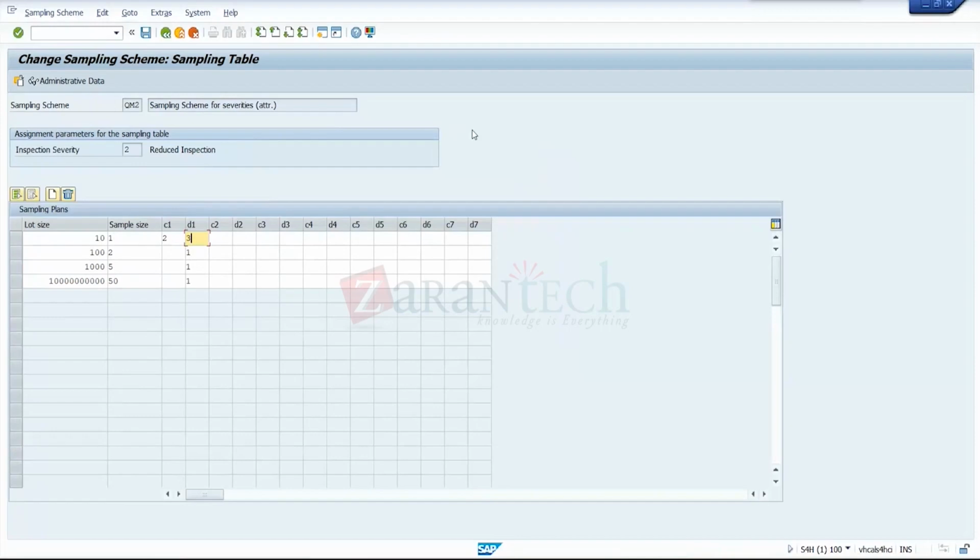D is there. Okay. So here I'll say if my sampling size is, oh, wait, not here. I have to give. Okay. Here 5 samples is there, no? So I'll give 2 here. 1 here. I'll give 3 here. So here I'm saying if one sample is rejected, then accept it. If 3 samples is rejected for that characteristic, then reject it. You're getting my point, right?